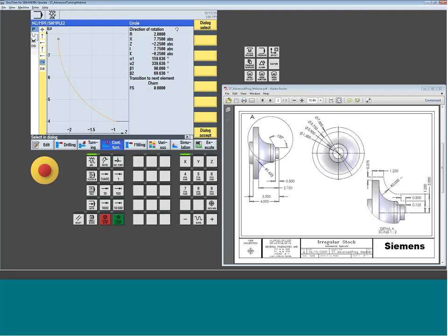So this is saying, is this the appropriate arc you want? There might be 2 different solutions. That's where the dialog select comes in. So you want to make sure you pick the one that's going to look like your print and accept it. And now what happened was not only did it fill out the rest of the information here, but it also calculated what that previous move would have been to have intersected this arc. That's obviously not tangent to that move.